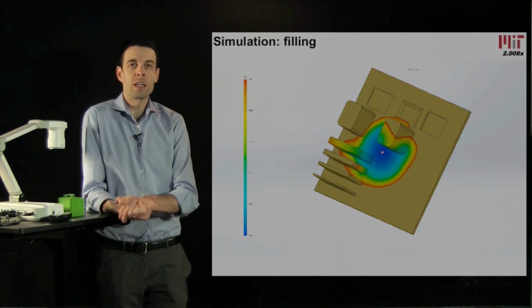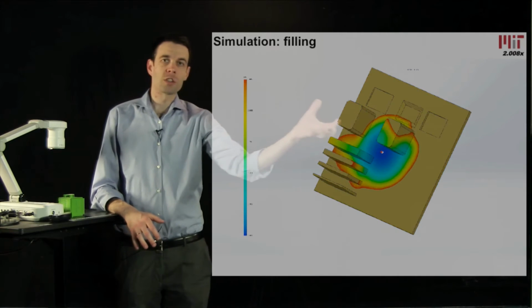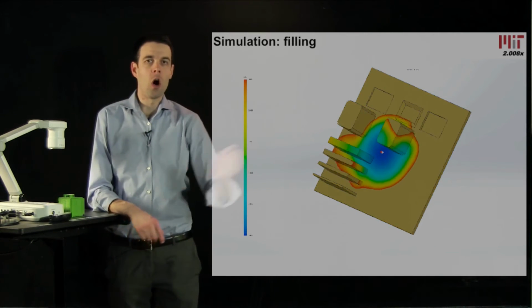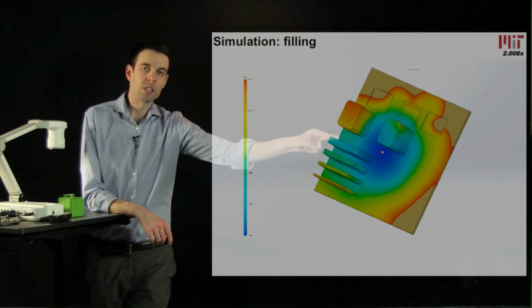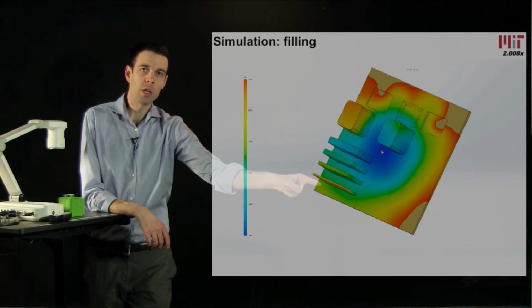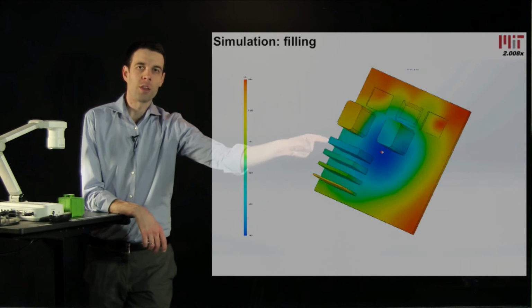The thinnest part in the mold is the most difficult to fill. Also, you see that the thick feature that's not cored out takes a while to fill because you imagine the plastic has to accumulate all the way through its thickness. And likewise, these vertical fins, the ones farther away from the center, fill more slowly, and also the filling rate vertically of the thinnest ones is a lot slower than the thicker ones.